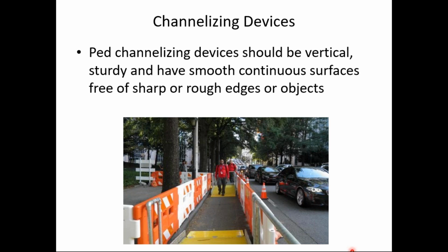If you recall my general rule of thumb earlier, I said use detectable warnings anywhere the curb is missing at a street crossing. So the way I would look at that is, does the driveway look or act like a street? If the driveway looks or acts like a street, then I would put detectable warnings. If it doesn't, then I would leave them out.